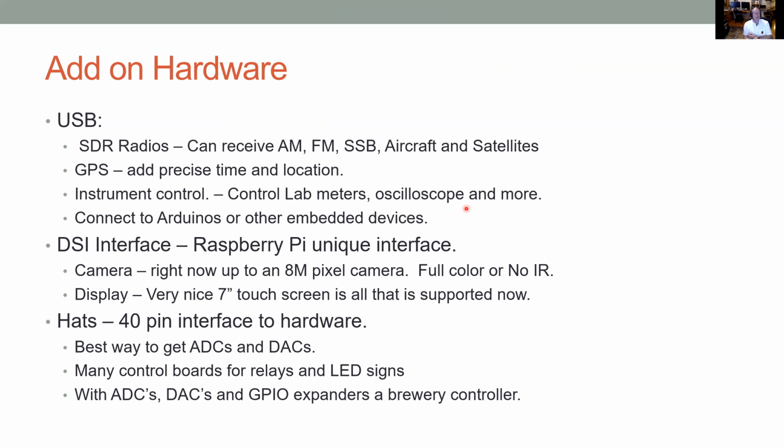Of course, over the USB, you can also control instruments. There's a whole set of SCPI commands that you can issue through Python and actually control meters, oscilloscopes, and more just by using the USB and controlling the devices. So you can actually make a little lab controller.